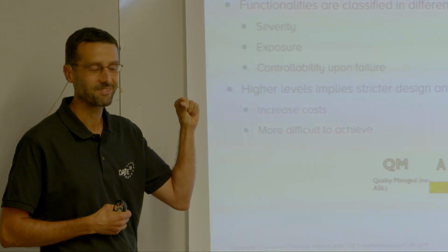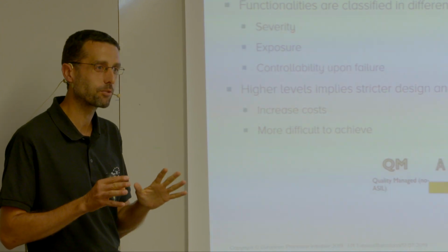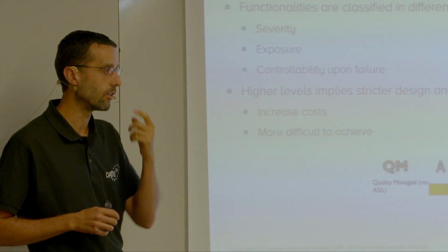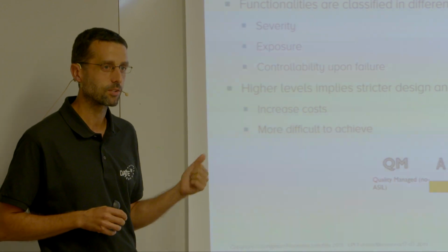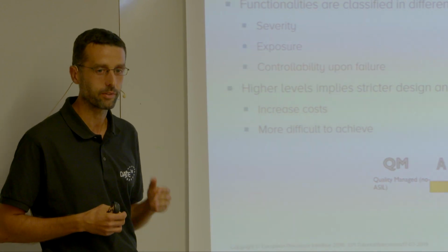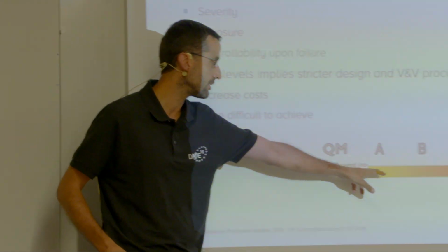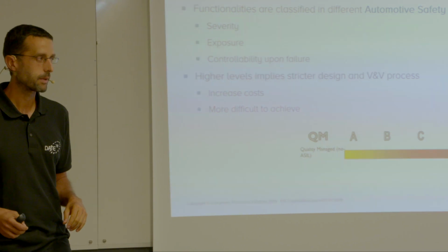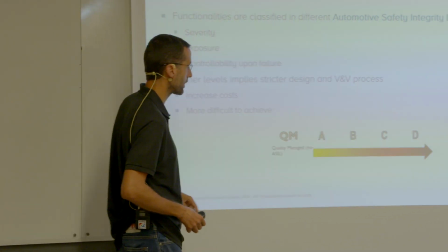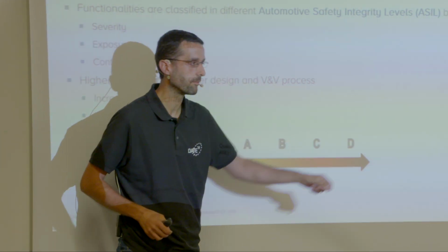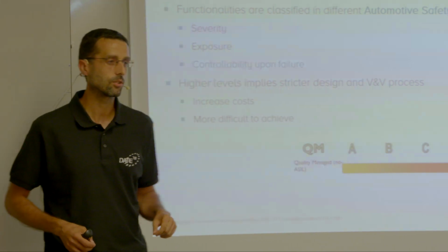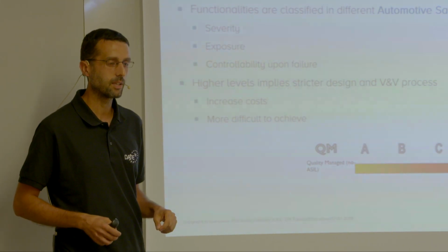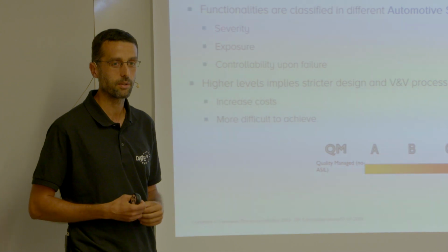Very little, okay? So basically, if you have to classify the criticality of your airbag system based on the risk of not opening when you have an accident, they will very likely say that it is ASIL A, that you need to verify that much. But the reality is that normally the airbag is classified as ASIL C or D, because of a different reason. What happens if the airbag opens when you're driving?